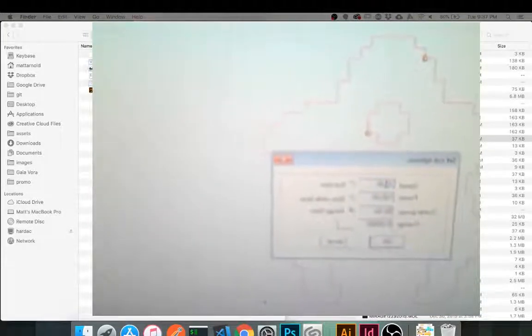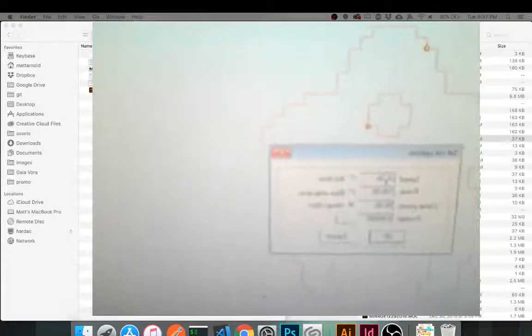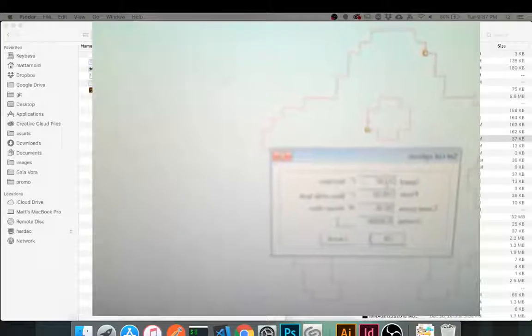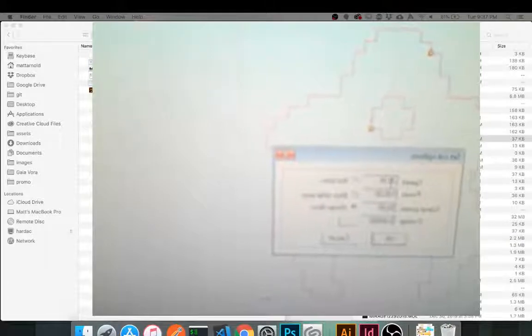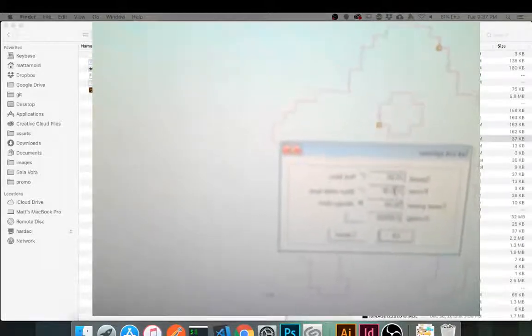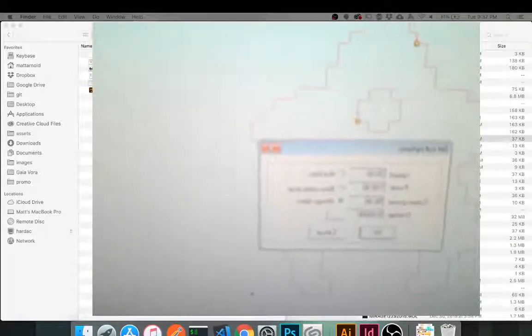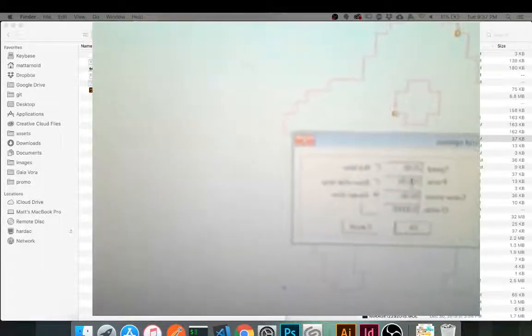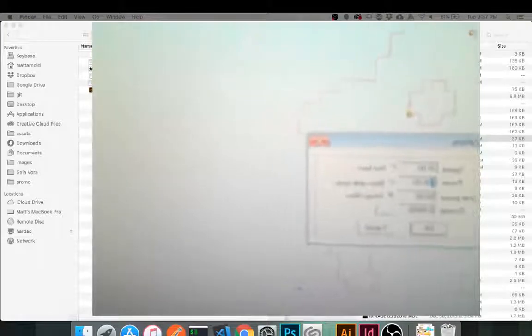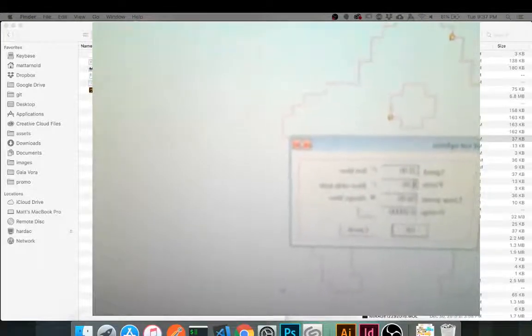If you go down to like 12 speed, you're probably going to light the wood on fire. So this is from 0 to, let's say, 400 speed. Usually 20 is fine. Here's power. All the way to 100 will give us kind of a charred edge to our wood. Let's just go ahead and be a little bit cleaner. Let's say I want just 80%.